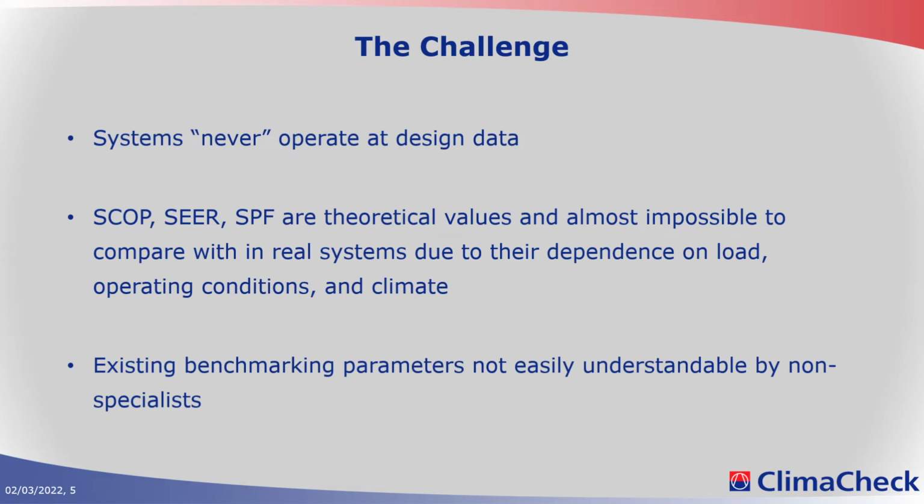An additional challenge is that systems never operate at design data. Manufacturers will include the design data, and the COP at this design data, but the systems will never operate at those conditions. We also have seasonal KPIs, such as seasonal COP, and these are theoretical values that take into account the whole season, what we get out of the system during the whole year or during the whole winter. Now, this is good information by itself, but it will not help us to know the performance of the system,